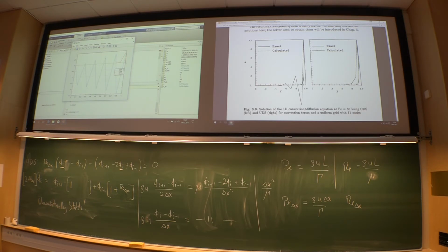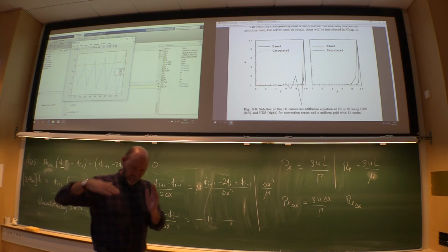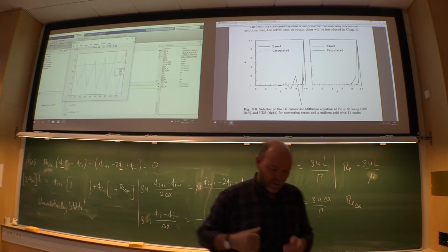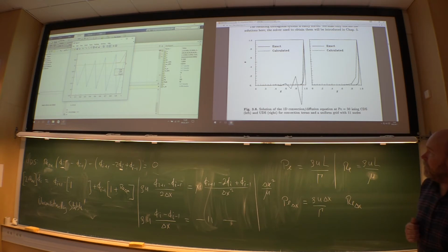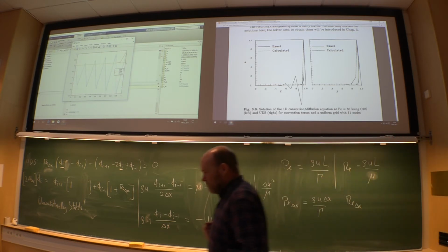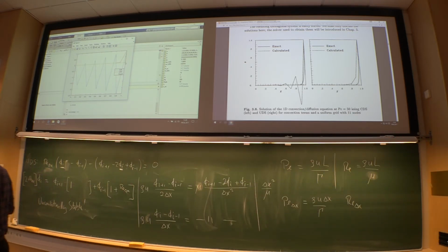So the higher the Peclet number, the higher the cell Reynolds number, the stronger this shoulder, you might say, will be. So that the harder the turn will be just down there in the corner. And it's far, far from it, of course it is. But it's stable, unconditionally stable. But the error is huge. While the central scheme is way off.